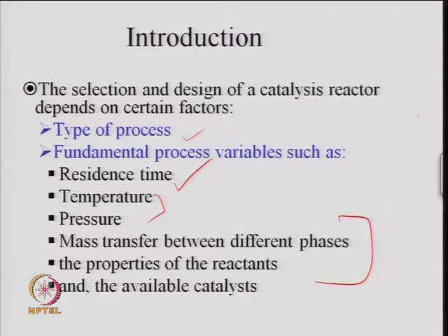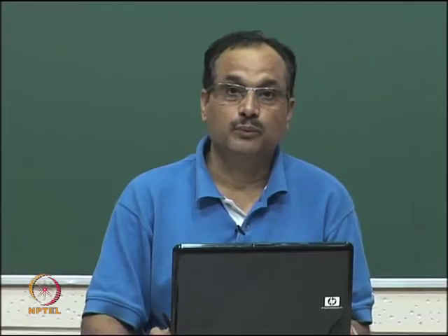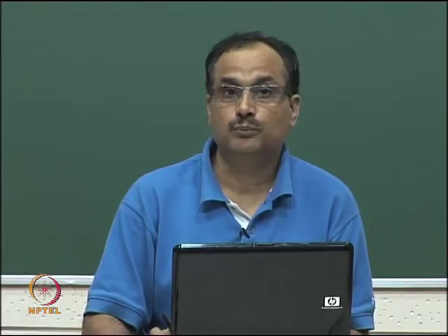And finally, which catalyst is being selected, in what shape, what size, and what are the properties of that catalyst in terms of porosity and other structural or geometrical properties, that also becomes very important for selection of the reactor.